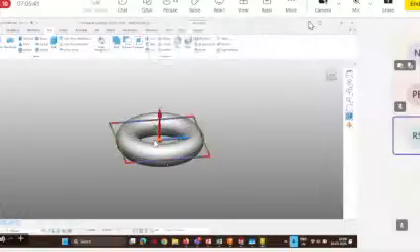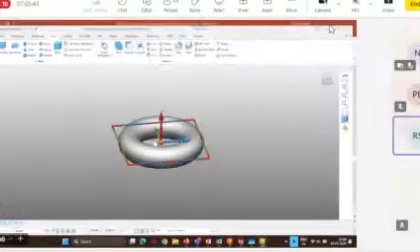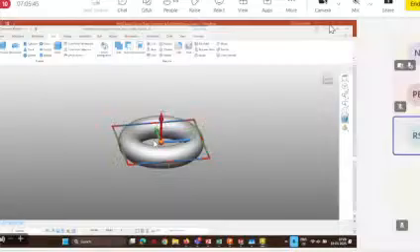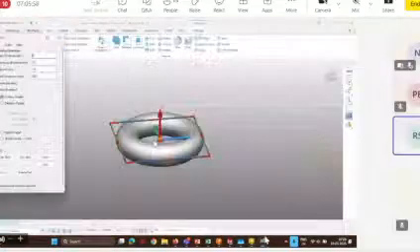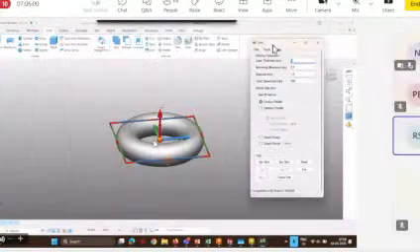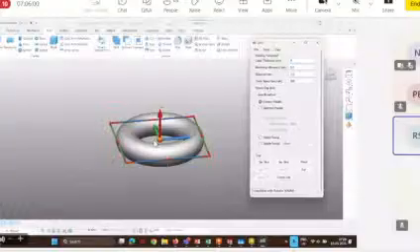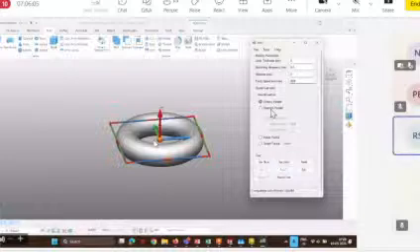Now we select this model and create this toolpath. We'll keep everything as it is. The step forward, we'll increase it to maybe 500, and bit 2 is fine. Then we'll go for the direction parallel with minimum lift.